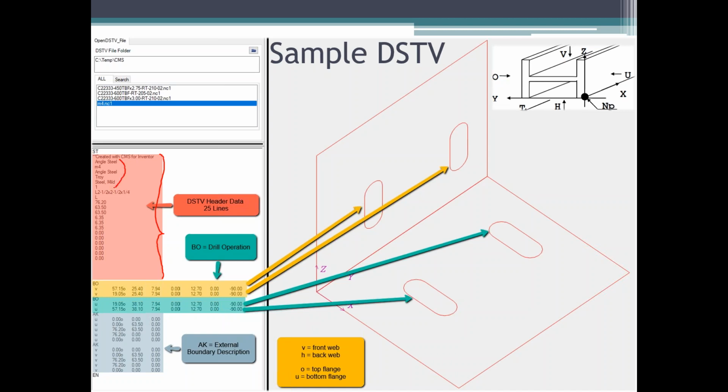For most cases, these are for bookkeeping purposes. It's not something technical that goes to the machine, but some CNC machines might be sensitive to those inputs. So you just want to verify that quickly on your end, and set this up on our CMS end so that you can map your iProperties correctly to your DSTV files.